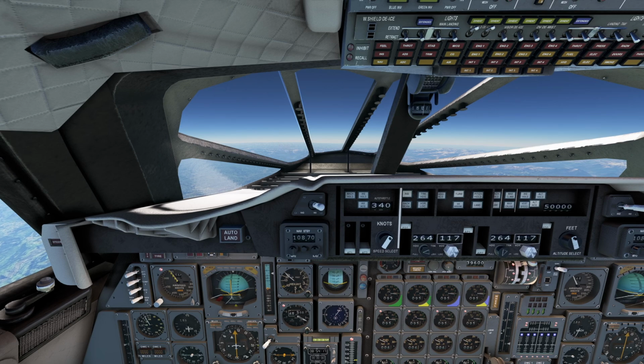At 50,000 feet, we're going to accelerate to Mach 2.02. We're going to indicate 60,000 feet, and then we're going to a mode that usually works okay, Mach hold. So actually the plane should keep the speed, 2.02 or 2.04 Mach, and steadily climb automatically to about 60,000 feet before we begin our descent.